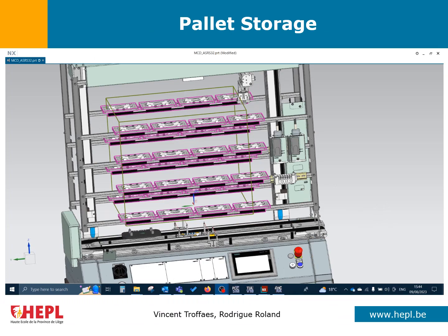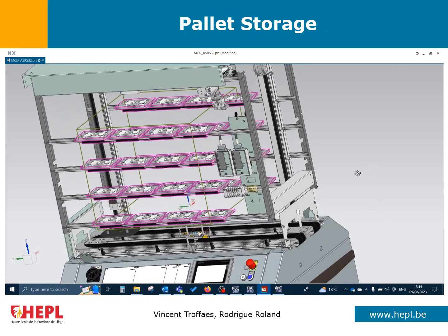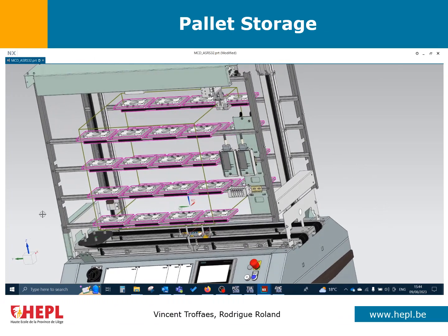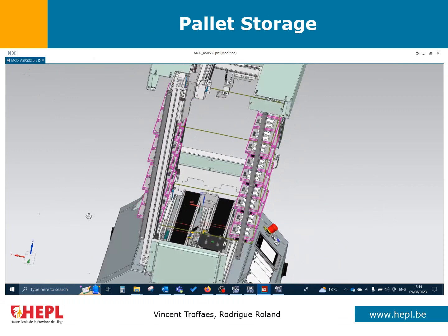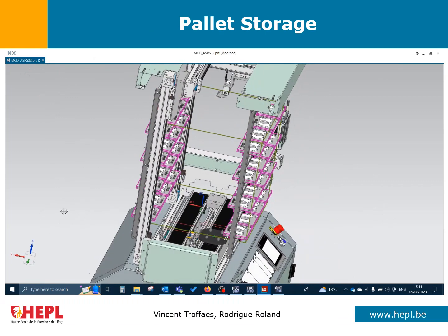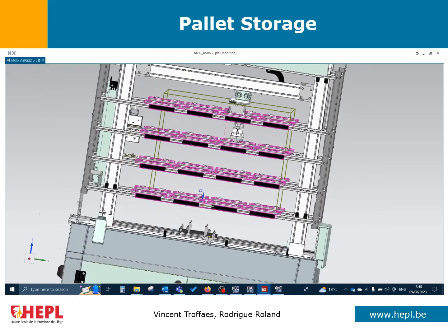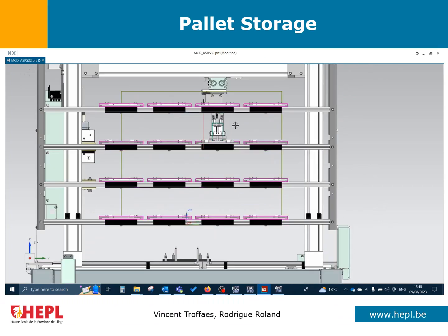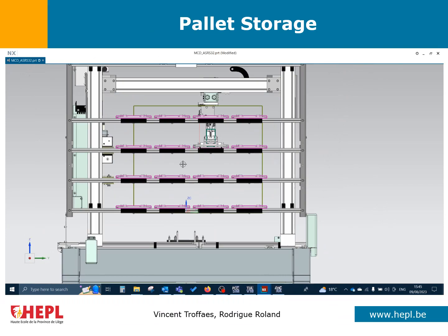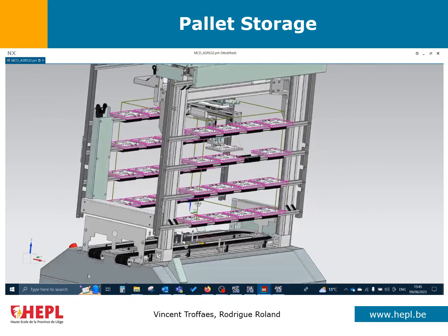So it's possible to completely emulate the servo drive behavior with Siemens SIMIT software, but we didn't have the time to try this feature. So in our case, we simply chose to command those sliding joints by giving an analog set point from the PLC. And we use position sensors to send back the position to the PLC as an encoder would do. The rotary axis was made of a hinge joint, so there is not much difference compared to the sliding joint. The only difference is that the vector is circular.